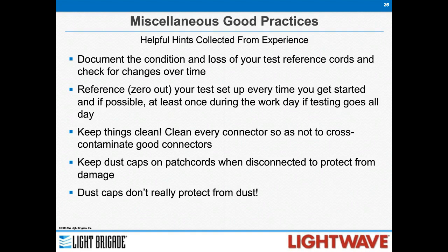And keeping dust caps on your patch cords when they're disconnected or anything that you're testing. Dust caps are there to protect from damage. They are not really there to protect from dust. They're really little plastic caps that have dust in them most of the time. So don't think that the dust cap is keeping your connectors super clean, but they certainly are protecting them, and they're certainly important. So make sure you don't lose them. Make sure you keep your connectors covered when not in use.